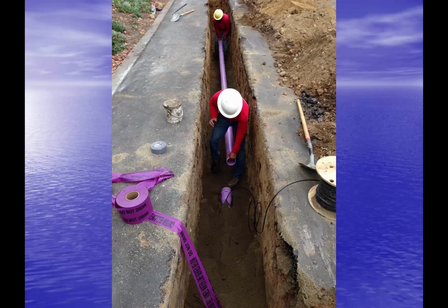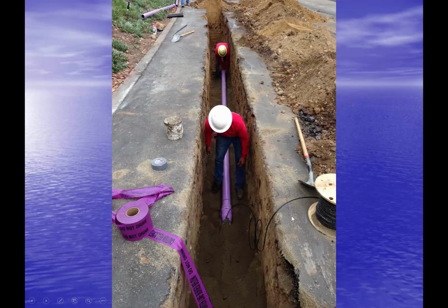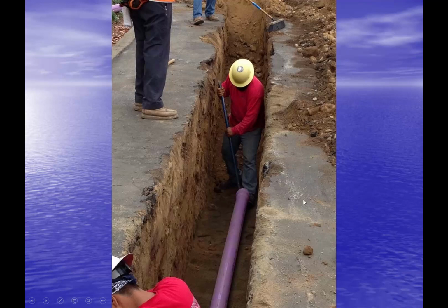So, a couple pictures of jointing pipe. You see the spigot end in the hand here. You can see the bell end down here. You can see that reference line on the pipe right behind where it's being held. Now the pipe's been inserted. The beveled spigot end is already into the bell. You can see that reference line again. And in this case, they're using a digging bar on the back end to push it home so that you get that full embedment and a good tight seal.